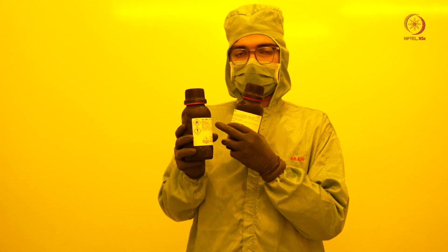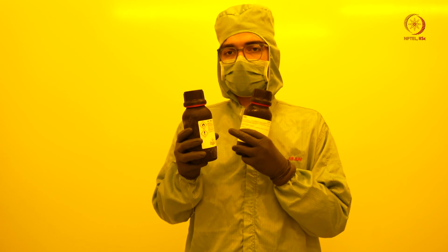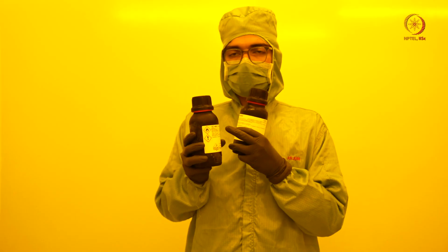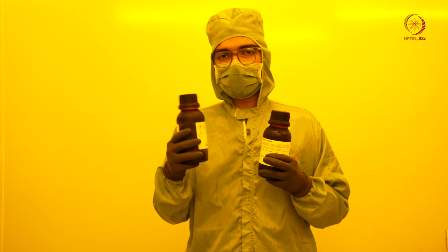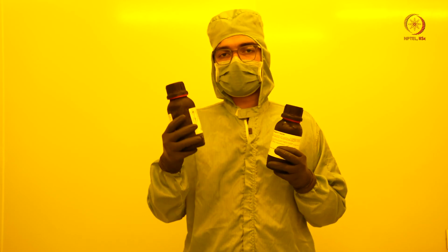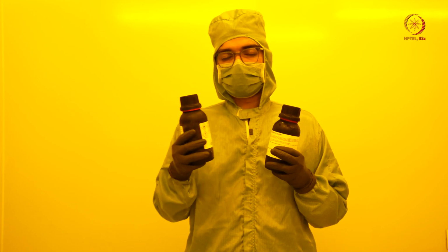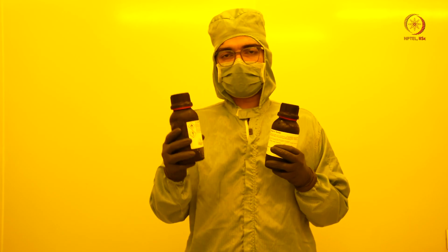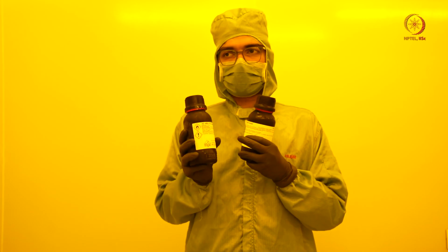The 62 at the end means that when we spin coat this photoresist at the recommended RPM, or rotation speed, you will get a photoresist thickness of 6.2 micron. So this is a very repeatable process. Now when we are spin coating, depending on the speed at which we rotate, the acceleration, and the duration of the spin coating, the thickness might vary. But for the recommended speeds, it would be 6.2 micron.